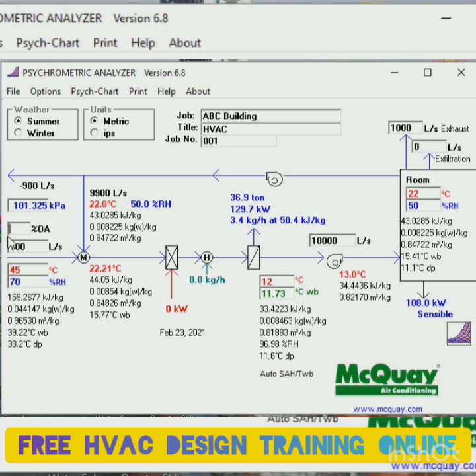See how much fresh air you require. Some rooms need 100% fresh air, but you have to see what kind of room it is. Is it a smelly area? If it is, we have to put 100% fresh air: 100% supply and 100% exhaust, because the smell cannot be returned back to the system. So here I'm just assuming the value of 10% only.